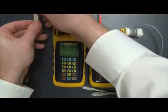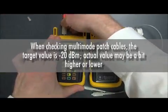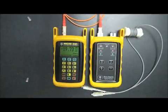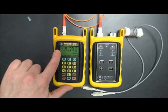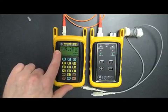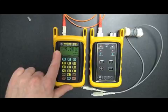Now, as far as the target power levels go, what we're looking for is a value of about minus 20 dBm. Now, minus 20 is where we calibrate our multimode light sources at. Now, that calibration also includes a mandrel wrap. As you'll see, this power level here is a little bit above minus 20, which is perfectly fine. As long as you're close to minus 20, the cable is okay to use.